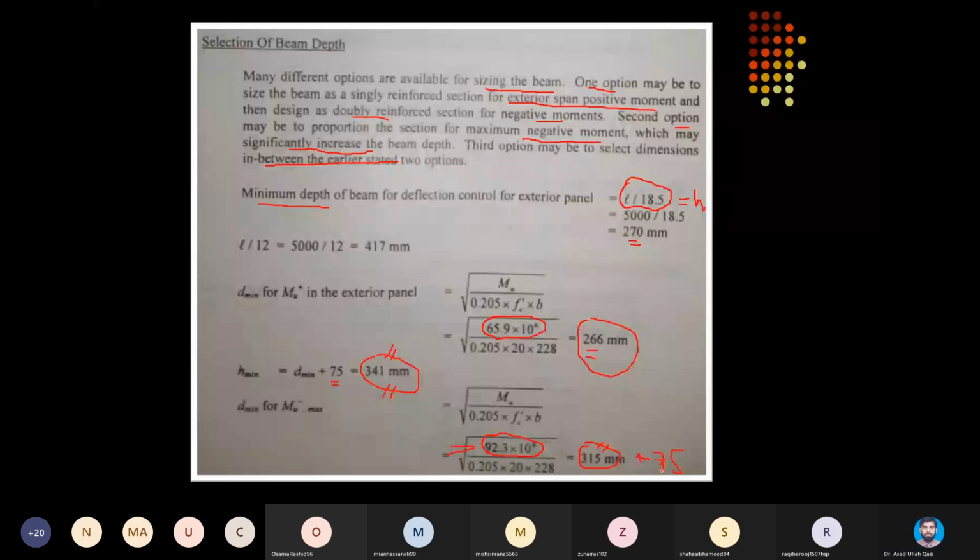to make a temporary formwork. And for even beam bottom, we will place bricks in a way to make this trench, which can later on be dismantled once concrete will be poured inside this trench by stacking the clay bricks one above the other.